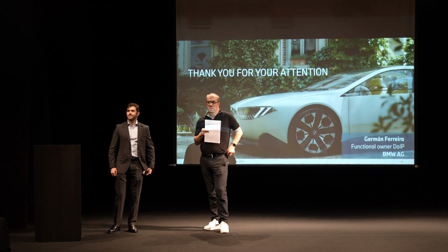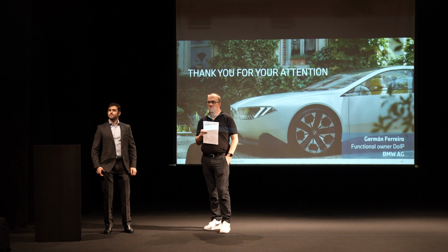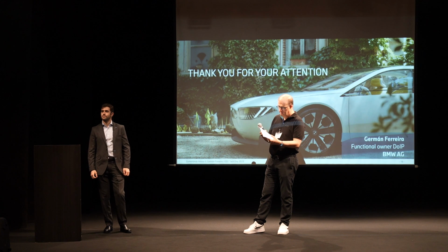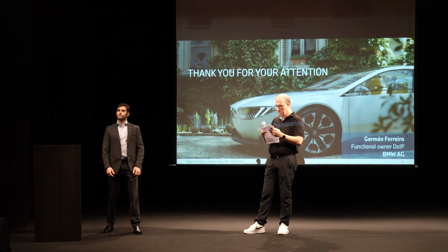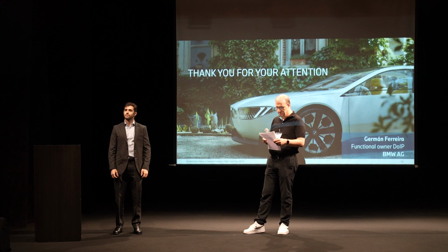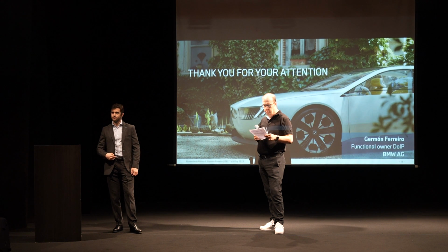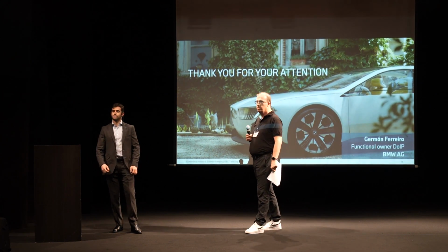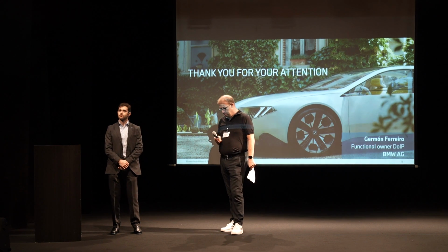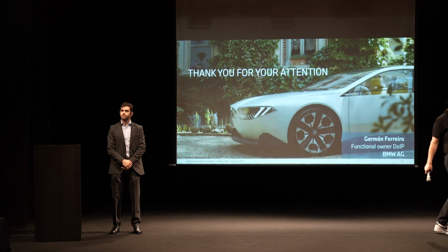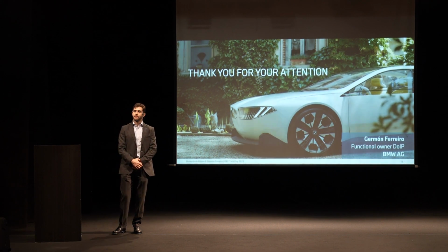Hi, Eric Parra here, Technique Engineering. You're mentioning that the DoIP implementation that you're proposing has to do with the structure on the gateway. I have a different question here. What about the physical layer interfaces on the OBD? Is there any guidance into, will it remain being 100 base TX with an activation port which is needed because the PHY is not EMC compatible? Or are there like more official approaches into integrating, like Thomas Koenigsegger proposed 2 years ago in the Automotive Ethernet Congress, 1000 base T1 directly on the connector? Is this part of the scope that you're looking at?